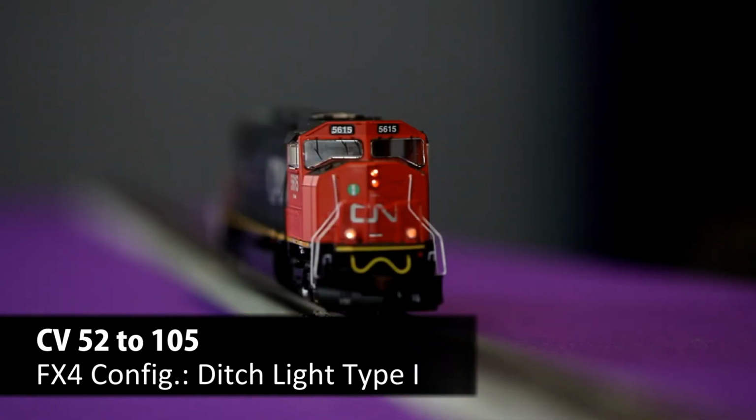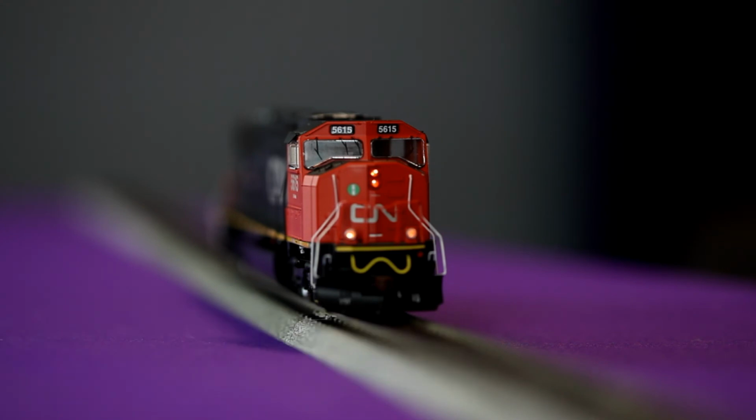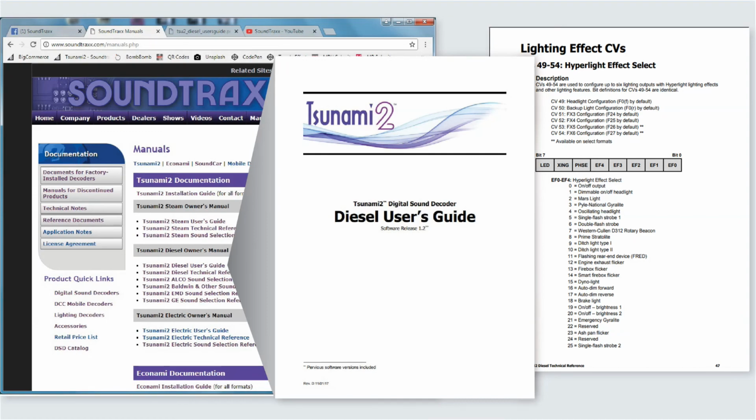Now the crossing logic means that I have to blow the horn, so when I blow the horn now, you're going to see the two ditch lights alternate and flash perfectly in sync. And then you can set what's called the hold time, and that determines how long that lighting effect lasts. So for more information, please go to our user's guide at SoundTraxx.com under the manuals, and you'll see how to set these CVs for you and your models.